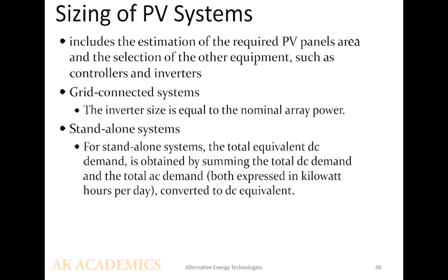Then let's move on and see how we can connect the dots and how we can size a PV system. The sizing of PV systems includes the estimation of the required PV panel area and the selection of the other equipment such as the controllers, the inverters, and so on. For grid connected PV systems, the inverter size is equal to the nominal array power.